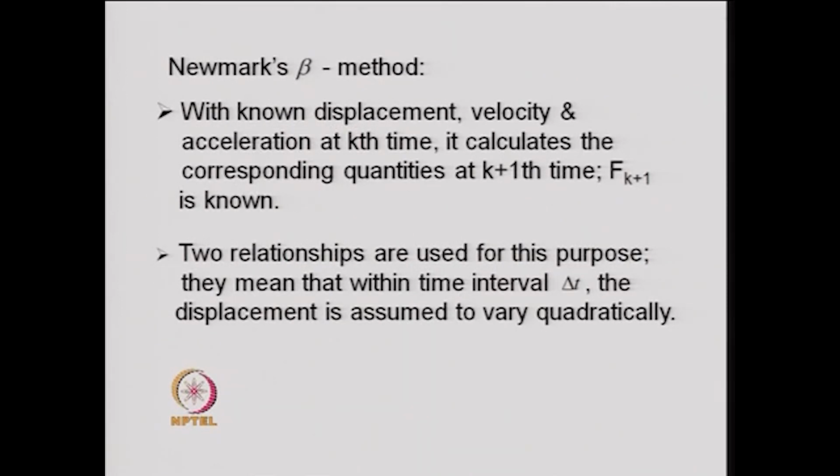So, that is the recursive form of the Duhamel integration, and it requires the solution of the problem for certain known cases. That is, the damped free oscillation, the solution for a rectangular pulse, which also can be obtained using Duhamel integral analytically, and the response for a triangular pulse, which also can be obtained using an analytical solution.